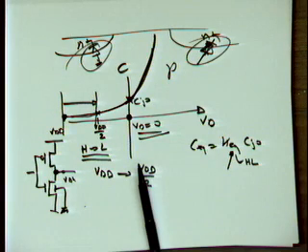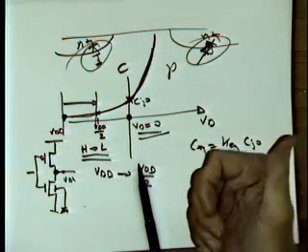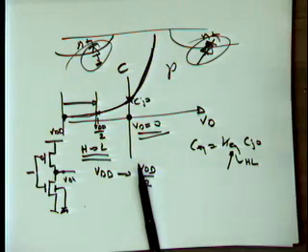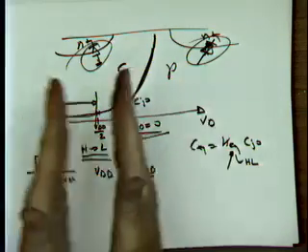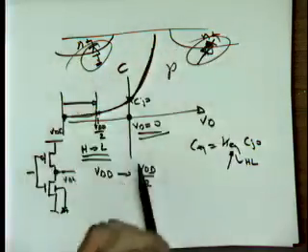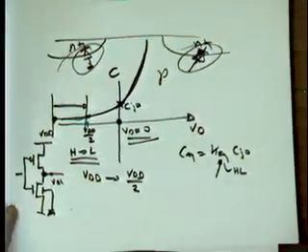The nice thing, however, is once you've done this for your technology, if you know your supply voltages, and you know the value of the phi's and all these kind of things, once you computed your K equivalent, you can keep it forever. There's 90 nanometer technology. I compute the K equivalent, store it in my computer, and we're done. We don't have to recompute it again because it's always the same, as long as I don't change the supply voltage, because then, obviously, the end points are going to change. Okay? Is that clear?